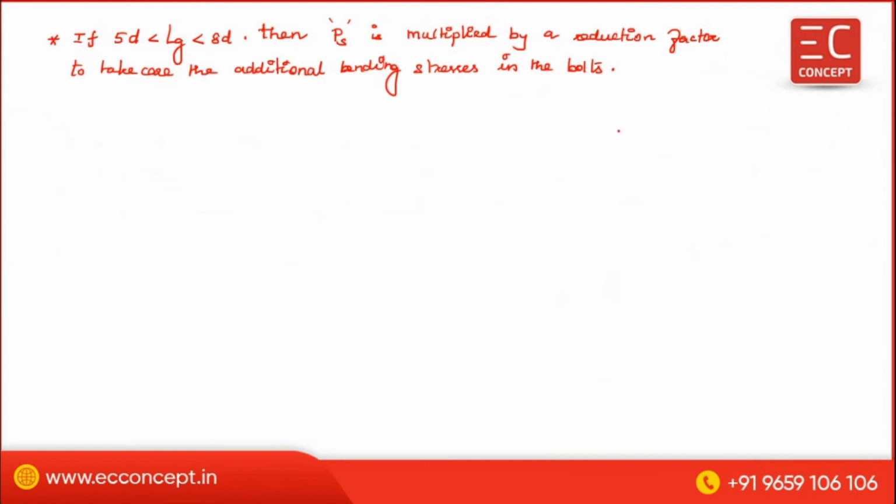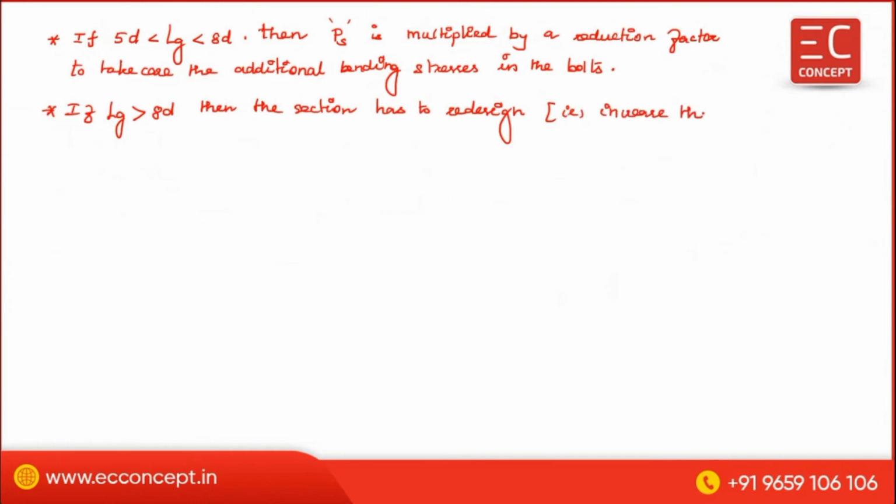Next, if LG is greater than 8 times the d, then the section has to be redesigned, meaning increase the diameter of the bolt.